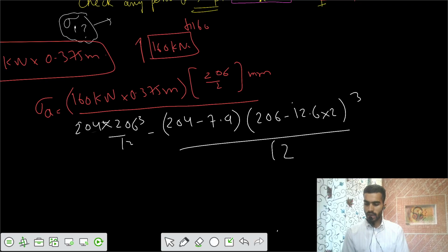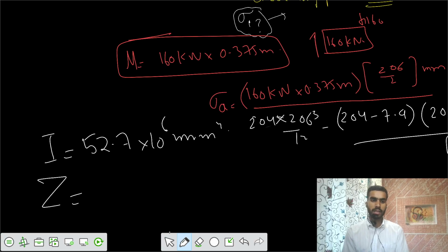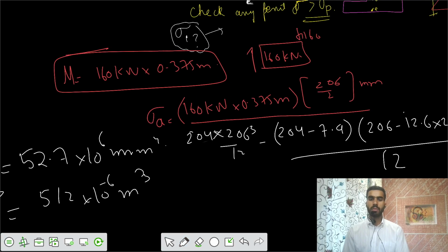That I value is already provided to you. The value of I is already provided to you. That's 52.7 into 10 to the power 6 millimeter to the power 4. And the value of Z is also provided. That's I by Y max. I by Y max is also provided to you. That's equal to 512 into 10 to the power minus 6 meter cube. So these two values are directly provided to you.